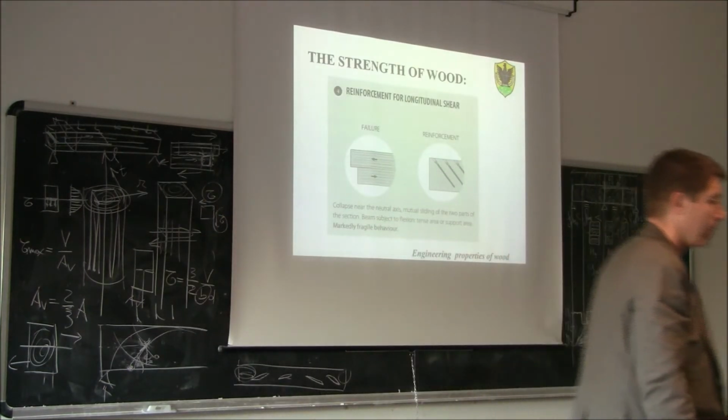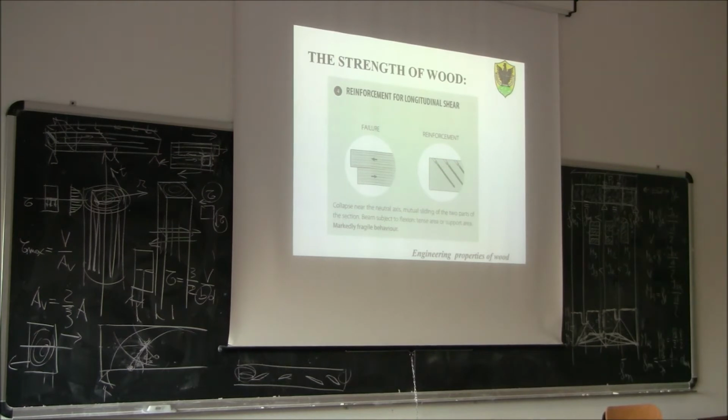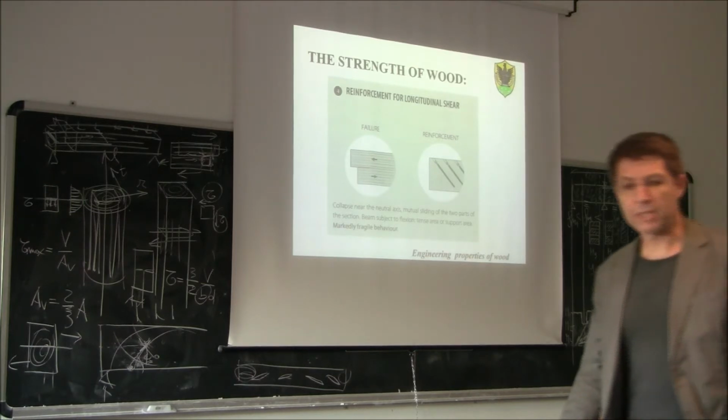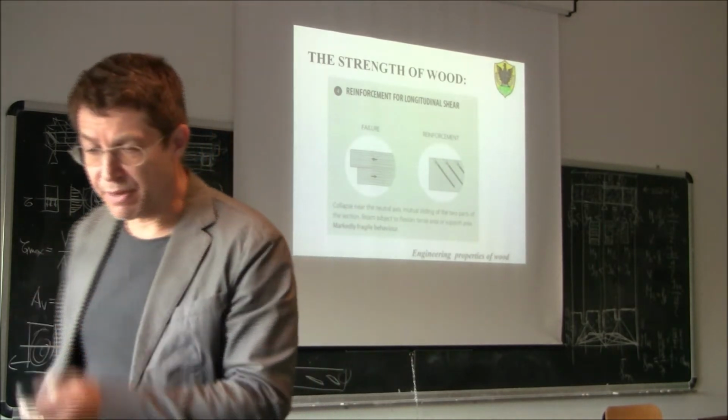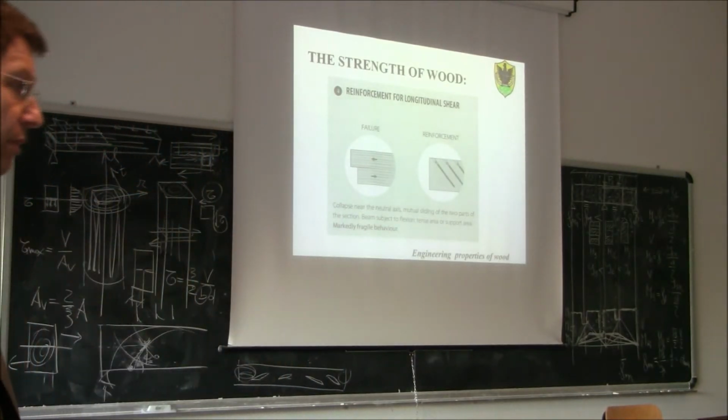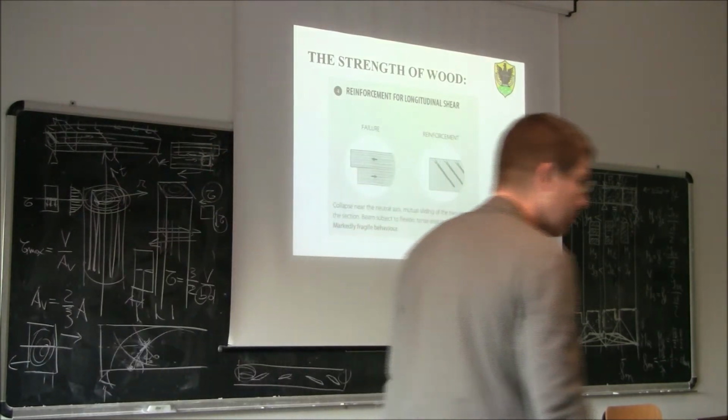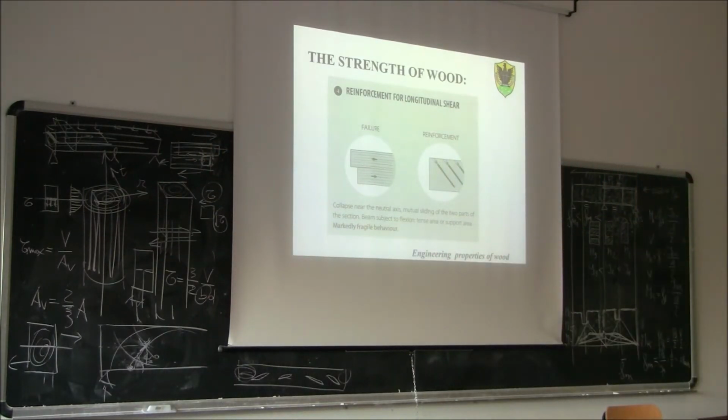So, how to avoid shear failure? We will see later in the course that there are some ways to reinforce a timber beam, not with normal reinforcement like in reinforced concrete design, but using some screws. So basically in timber, very often we use self-tapping screws, which means viti autoperforanti, that we can screw inside the timber, and these screws may provide some reinforcement against shear.